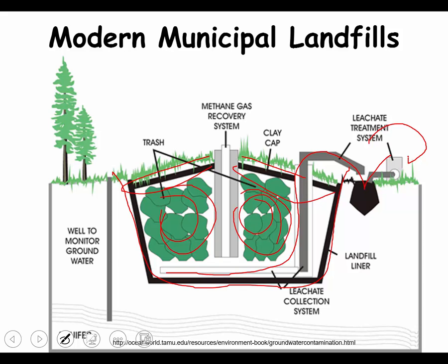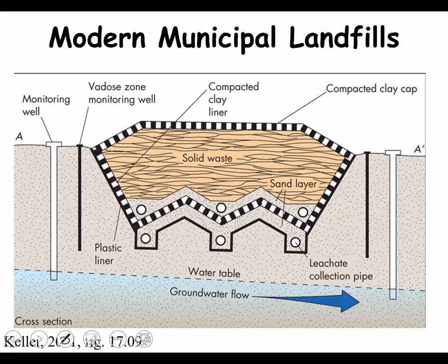The gaseous portion is methane. One of the byproducts of modern landfills is methane production, and so that's coming out here, and so you're trying to recover that. In old landfills, it might come out by filling your neighbor's basement and your neighbor's house blows up. So this was a major problem until we started capturing it and treating it.